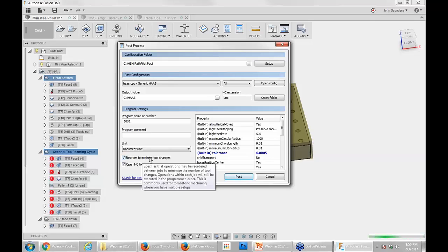Of all the things I've done, to be conservative, when I first run this on the Haas, I will go in after I probe my Z heights for my 3 or 4 offsets. I will add 3 or 4 inches of Z, or probably pick a number, 3 inches, and I will air cut all of these, just to make sure, because for me, not having a huge amount of confidence and venturing into unknown territory. For instance, there was a very small bug early on where the probing wasn't updating the coordinate locations doing midstream probing with multiple offsets. That quickly got fixed. Kudos to the Fusion and HSM team for getting that fixed so quickly, but I'm glad that I had air cut first to make sure I saw what was going on.